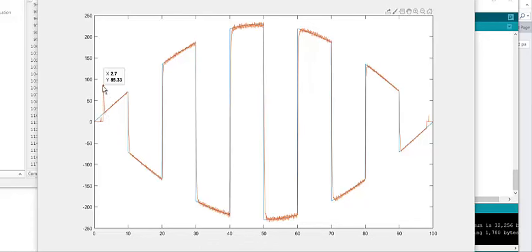So there is the initial overshoot there, and you can change gain values and try to optimize it more. And there is some jitter there, oscillation. That's just due to friction. You can't really do much about the friction unless you can find a way to reduce the friction there. So that's about it. Yeah, that's the PID controller.